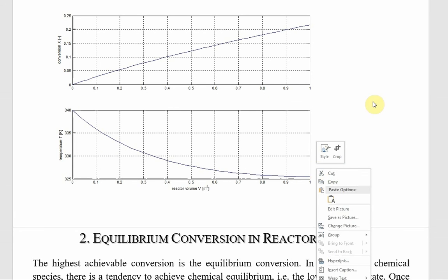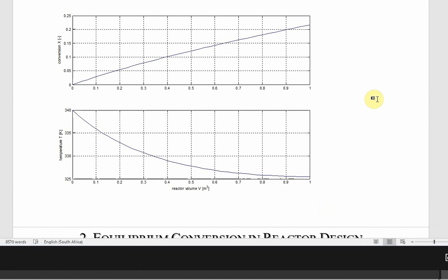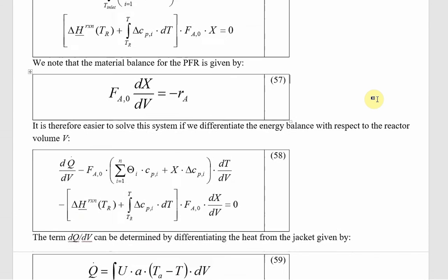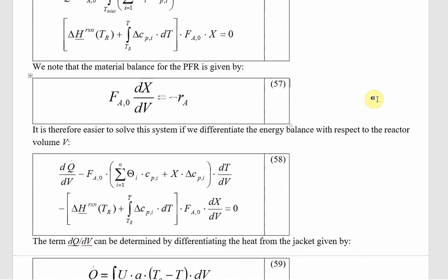Any questions or comments there? If we went back to first do the initial mass balance, and the generation term was the integral of r_A dV, before we would just say r_A V for the control volume, because we said that the reaction term was constant with respect to all the places in the reactor. So how can we start with first principles now, knowing this, because we can't any longer just say r_A V?